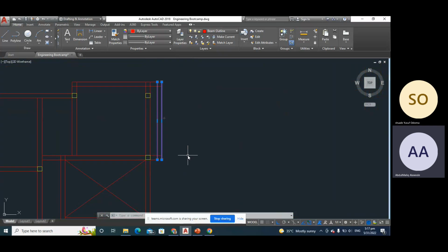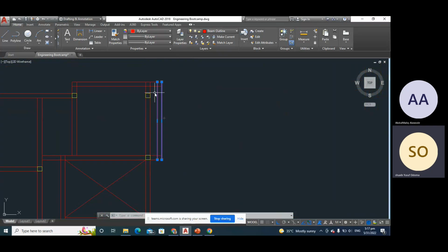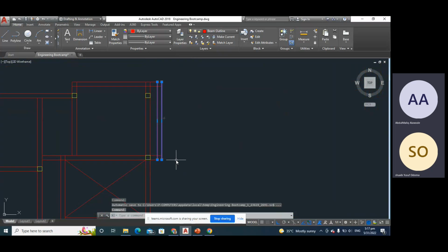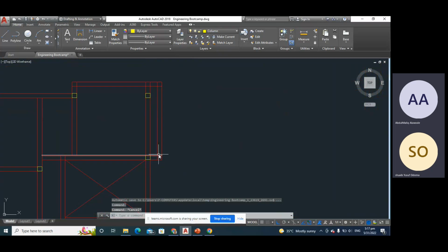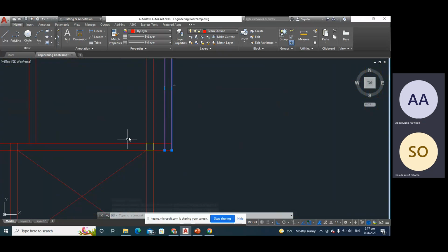It's a simply supported beam, correct? Yes, sir. But it's supported by two beams. Okay. So it's actually a secondary beam to two other primary beams. Okay. That's what I want to hear. It's the term that I want to hear: primary beam, secondary beam. That's a technical word. Do you understand? So here at this junction, this beam is actually a primary beam to this beam. Sorry, it's actually a secondary beam to this horizontal beam, to the horizontal beam itself.